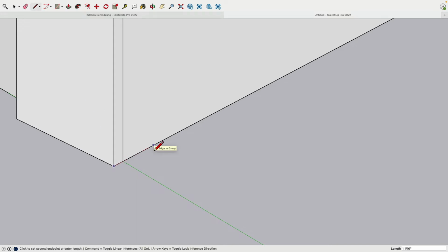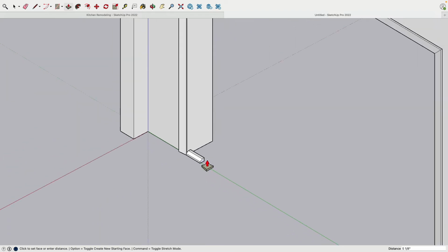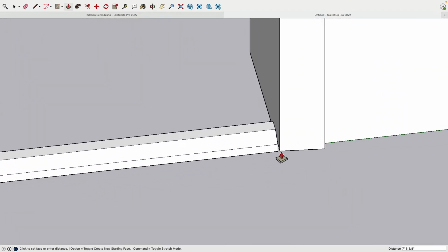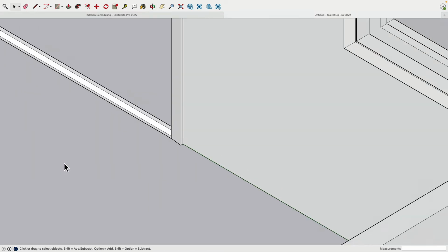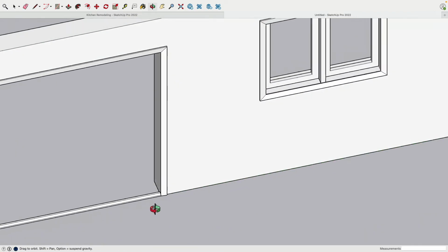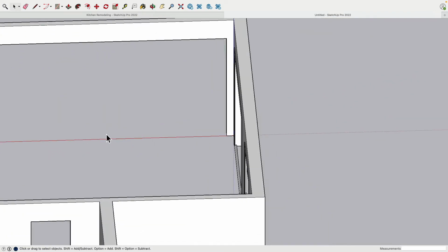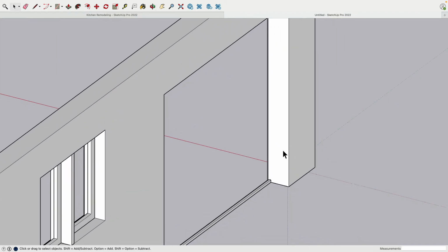First, we're putting down the threshold, 1.5 of an inch. And then this goes up 1 inch. Then here this goes up 1/2 of an inch. Now this horizontally 0.75 of an inch. And then we connect this. And then this we can drag out. Again, this is a piece that symbolizes, hey, there's a threshold. Okay, so now, next thing.